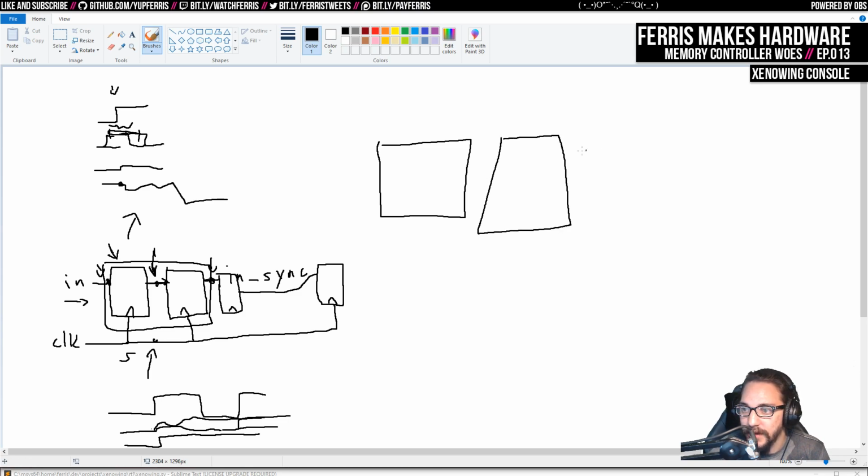If you have this part of your design hooked up to 150 megahertz clock, and even if this is in the same chip, and then this part of your design at 50 megahertz, then these clocks are probably going to be out of phase, even if they're very close or one's just a multiple of the other one. There might be trace length differences between the different signals, all kinds of stuff. So it might be really hard to guarantee that those are actually synchronous with each other, even inside the same chip. So these signals that go between here also need to be synchronized.